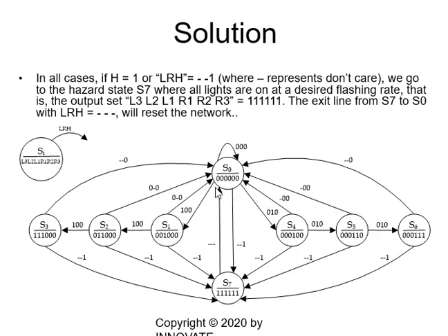Once we start the left light pattern, 1, 0, 0, we go to S1 and light left 1 will be on. Then we continue with the input 1, 0, 0. It means the lever of the left hand is still on. So we activate left 2 and 1, then left 1, 2, and 3 with S3. Then if the hazard is still 0, we go to S0, and if the left is still 1, we go through the cycle again.